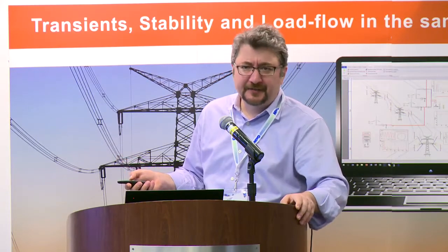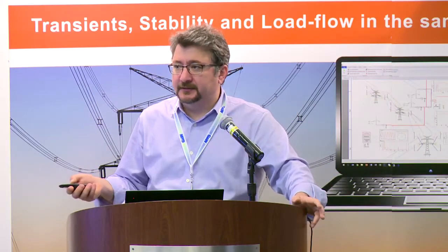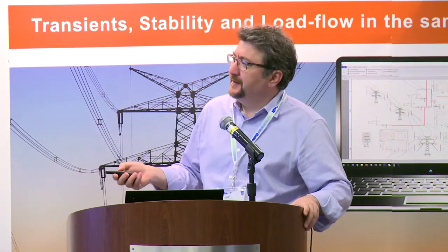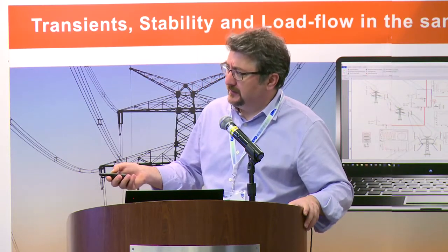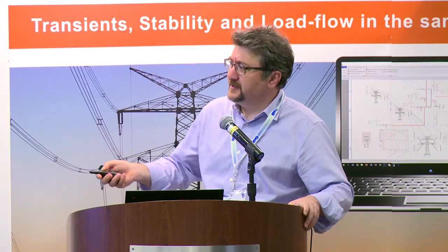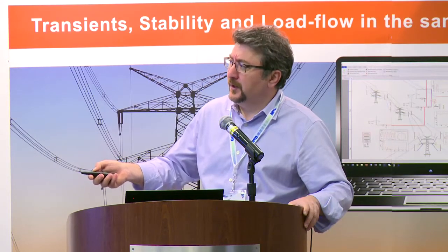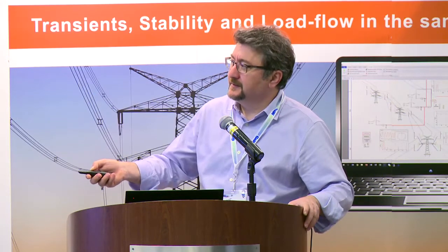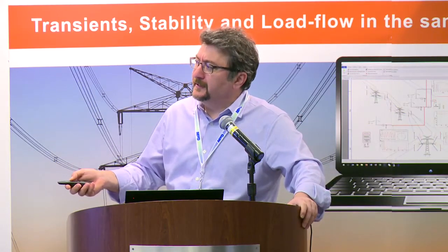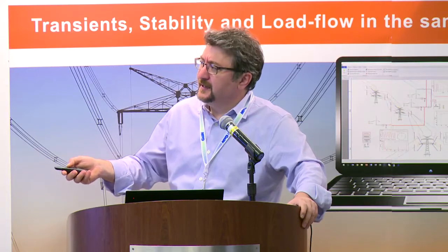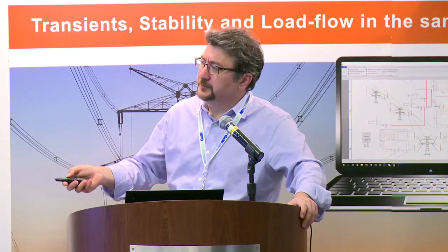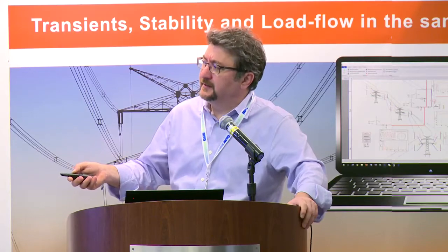Thanks to this, we can achieve modeling any number of conductors. There is no such tool, I guess, right now other than EMTP. So if you have 50 cables, it is okay. And then we have state space, propagation function matrix, characteristic admittance matrix, and nodal admittance matrix. These two things are used in frequency-dependent line models. So in distributed line models, basically the propagation function and characteristic admittance matrix. Using these, you can obtain the nodal admittance matrix for steady-state studies. But basically, these are the two things that allow us to model a line in time domain.